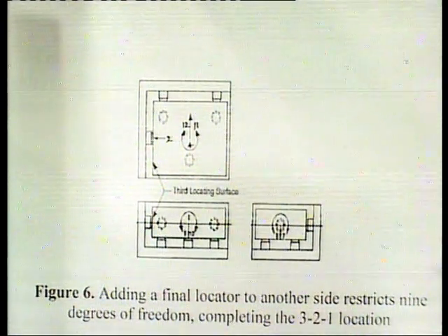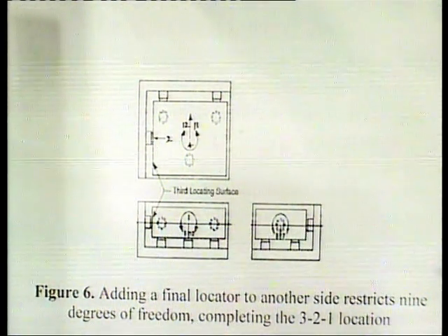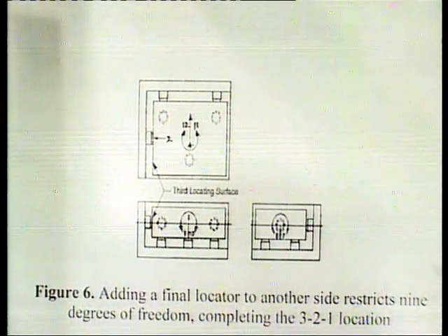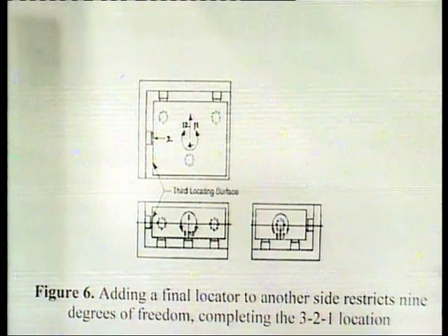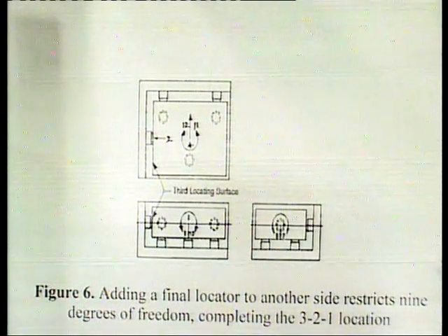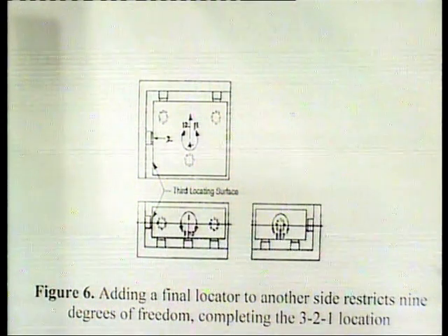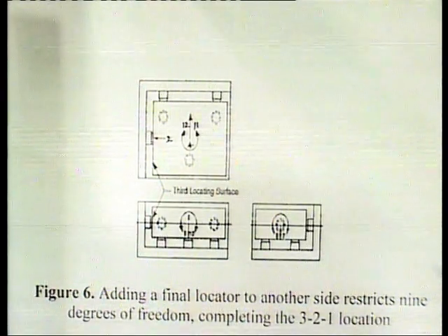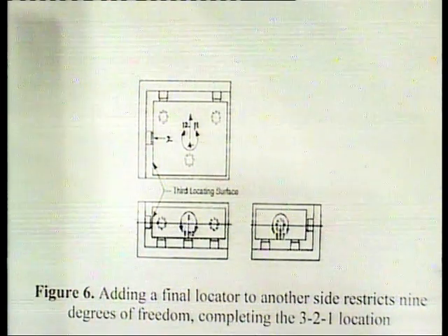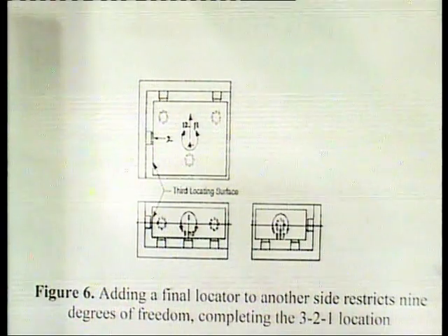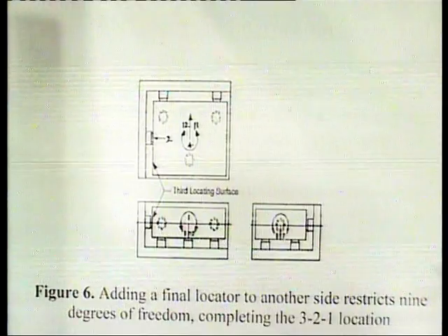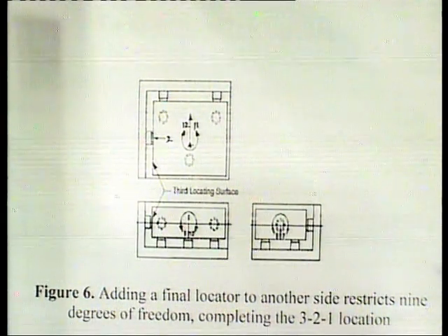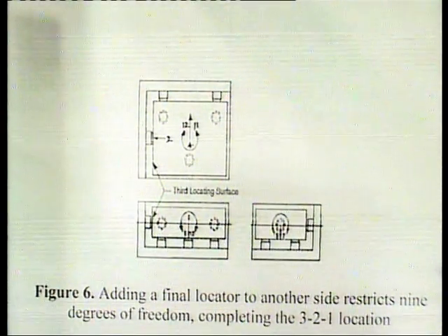Although cylindrical rest buttons are the most common way of locating a workpiece from its external profile, there are also other devices used for this purpose. These devices include flat-sided locators, V-locators, nest locators and adjustable locators.